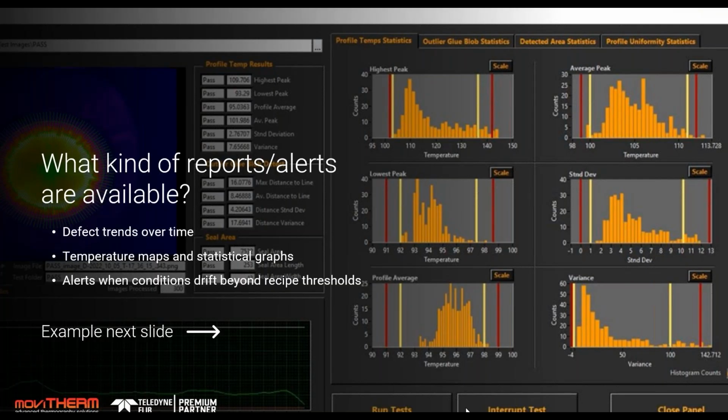Obviously, when you get a failure, it's going to reject the bottle. So you'll get the reject, and then you can go ahead and test it and inspect it. But you're going to see warnings, and the software's going to tell you exactly, on a certain run, how many went into the warning level, how many were failed, how many were good, and then it stores every single one of the images. And again, as I mentioned before, every image has hundreds of thousands of temperature points on there. So we can go back and do an analysis on the images that have been taken.